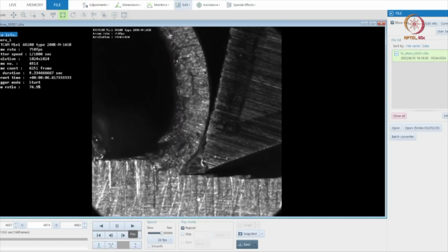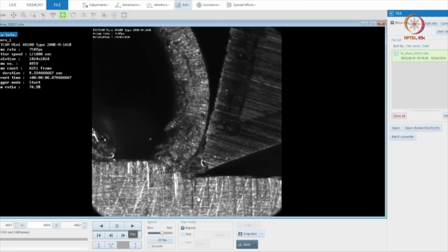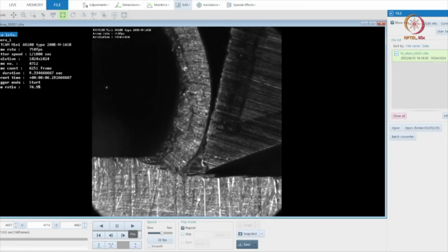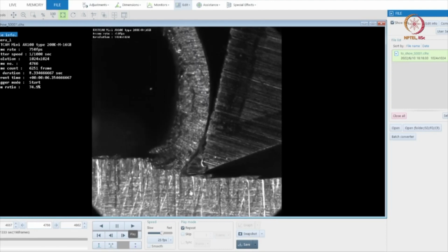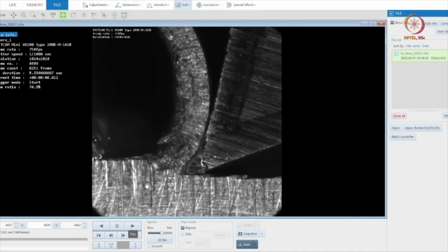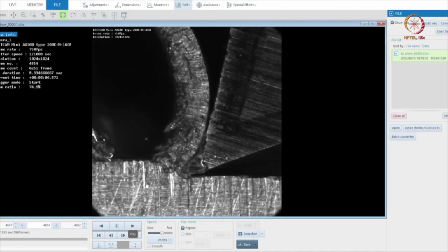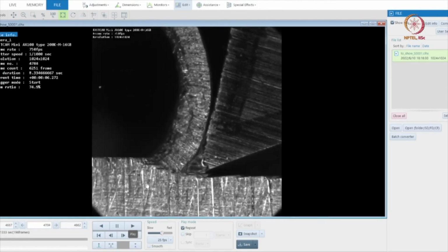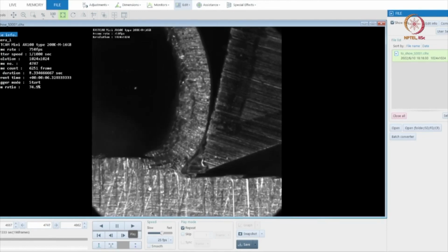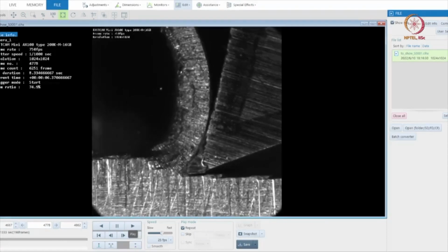So according to the calculation we have seen that we need a minimum of 700 FPS to ensure 6 pixels of displacement in between two frames. So I have chosen a frame rate which is a bit larger than 700 FPS, that is 750 FPS. I hope the first configuration was clear.